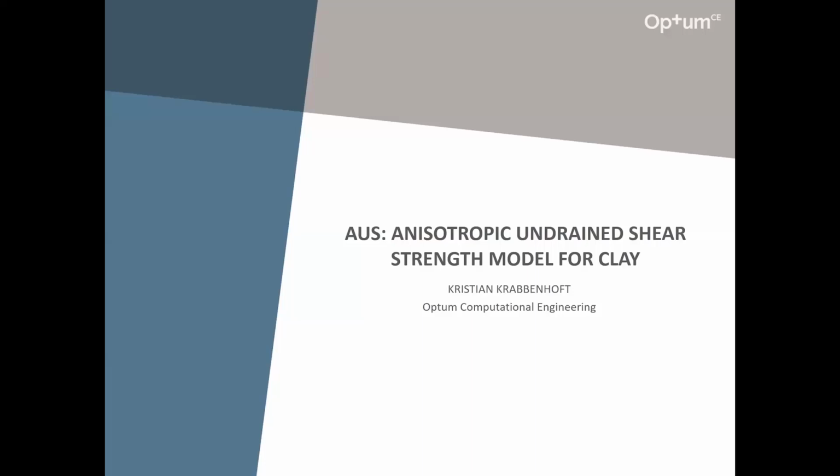And with clay, with undrained shear strength of clay, it's much the same. In plane strain, we have the plane strain undrained shear strength. And when we move into 3D, then the question is, what is the undrained shear strength in, say, triaxial compression versus triaxial extension? Are they identical, or is there a difference? And that's what this webinar is about, and it's what this model that Jan mentioned, the AUS model, addresses.